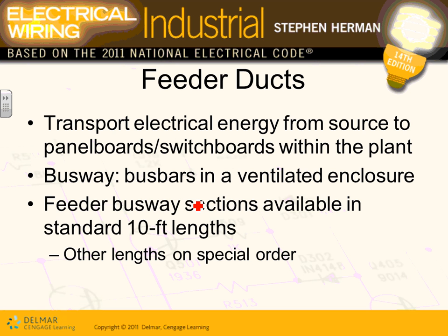So the most important purpose of busways, guys, is to transport electrical energy from the source to the panel switchgears within a plant. Like you see right here, I'm taking a feeder busway going right through my plant, and then a plug-in busway that all machines plug into. Instead of bringing every machine branch circuit into the panel, I bring the panel to the machine. Right at the top of the machines, I put my panels in the form of a busway, and with a fuse switch and an SO cord, I can plug in all my machines.